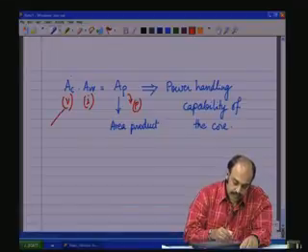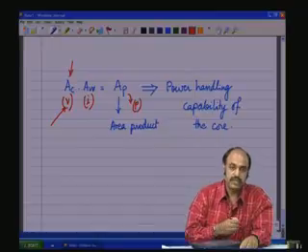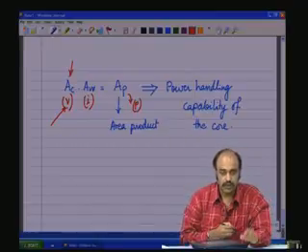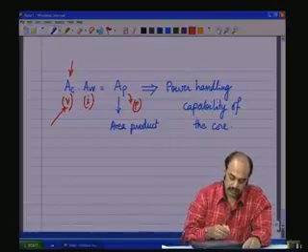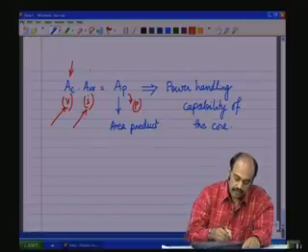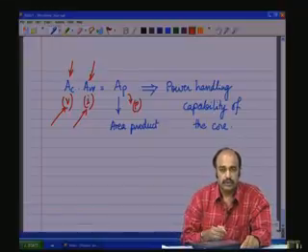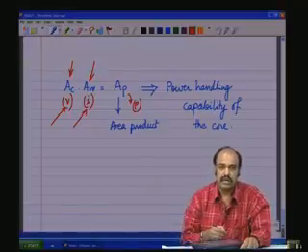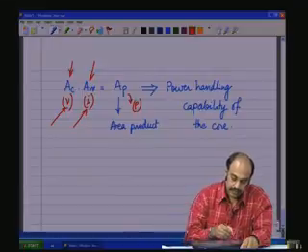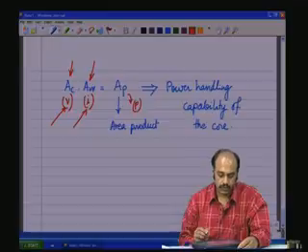This is the electrical parameter, voltage, which is trying to map to the physical dimensional parameter of the core called the cross sectional area of the core. Another electrical parameter, the RMS current, is trying to map to the window area of the core, another physical dimensional quantity of the core. AC, AW and sometimes AP are given in the data sheets of the core.